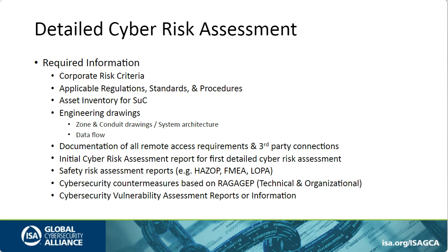You want to have your zone and conduit drawings, your system architecture documented, your data flow diagrams, what data flows are required, documentation of all remote access requirements as well as any third-party connections that are planned, initial cybersecurity risk assessment report from the initial, safety risk assessment reports, whatever they happen to be, whether it's HAZOP, FMEA, LOPA, et cetera, and what countermeasures are in the scope based upon recognized and generally accepted good engineering practice, or RAGAGEP,